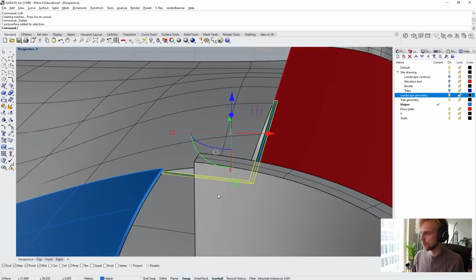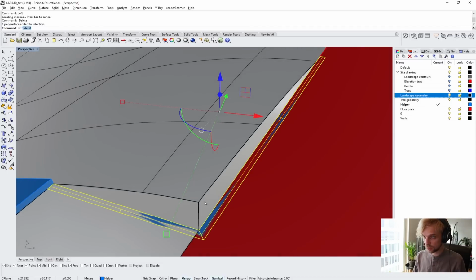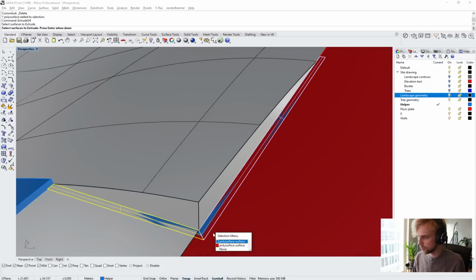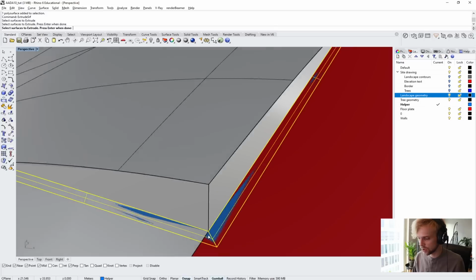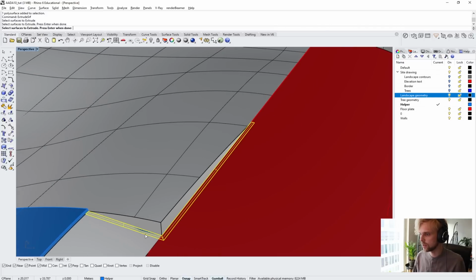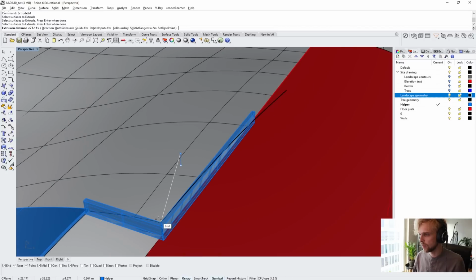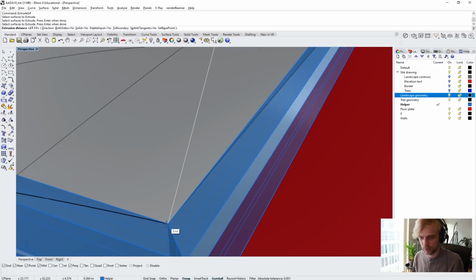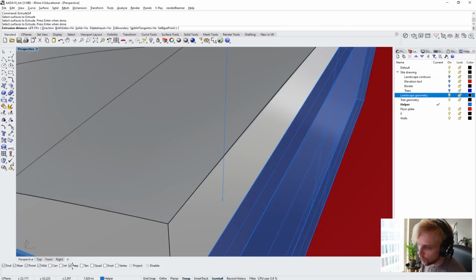And then I will just use extrude surface, select. For some reason it became two surfaces. I think that's because of the sharp corner. That's fine. Extrude both of them up until they reach the top here, and then just add a little bit more. So how do you know the actual height, how much you're extruding while you're snapping to a point? Well, look at this number here.